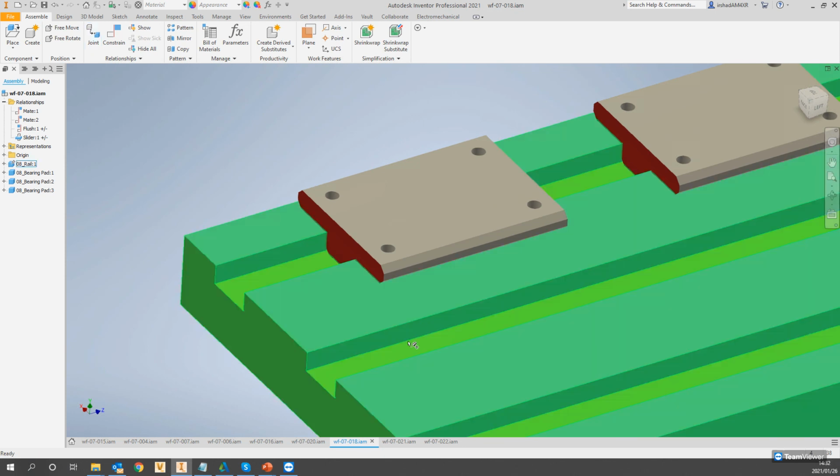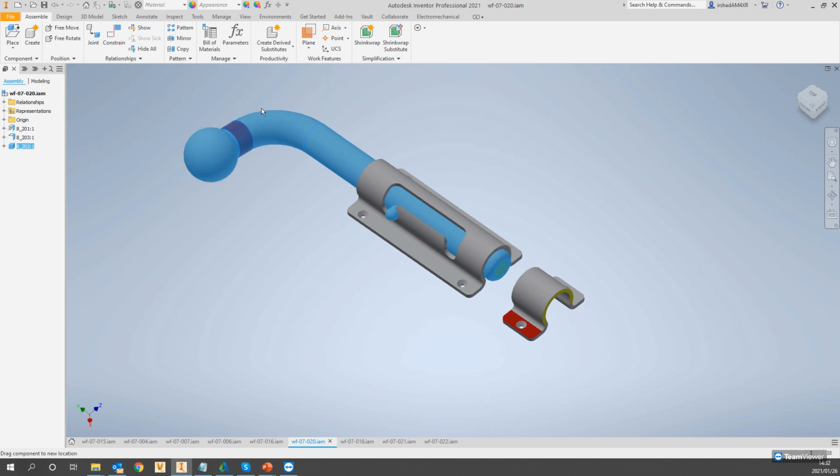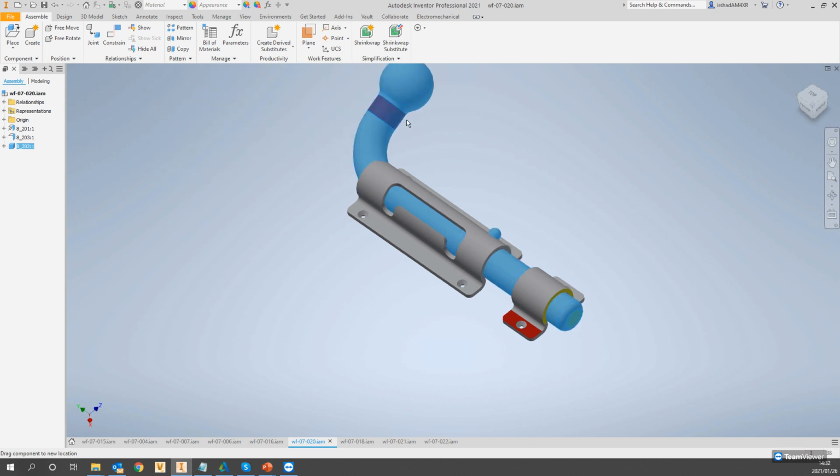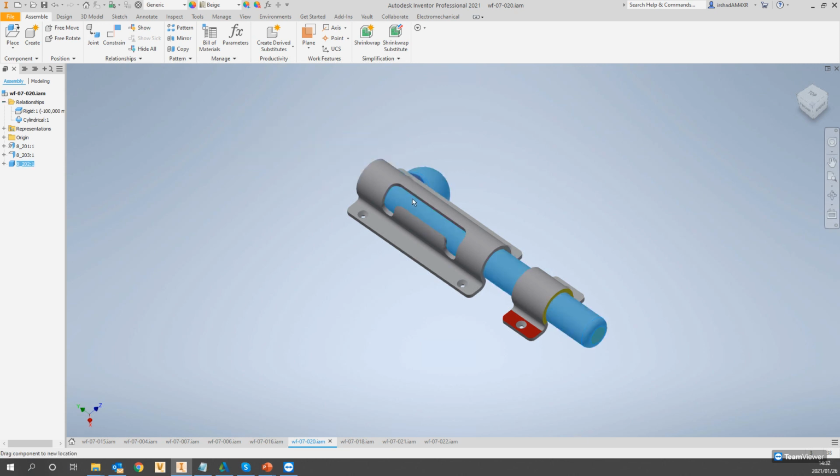Okay, and that was basically it. So I will go back to our example. I'll do the same thing again here. Okay, so we've inserted a cylindrical type of joint, whereas in the previous one we did a ball joint. I'm going to use the limit as well as contact solver. We'll see here that we can extend far too much. So let us just make a limit from there and there.